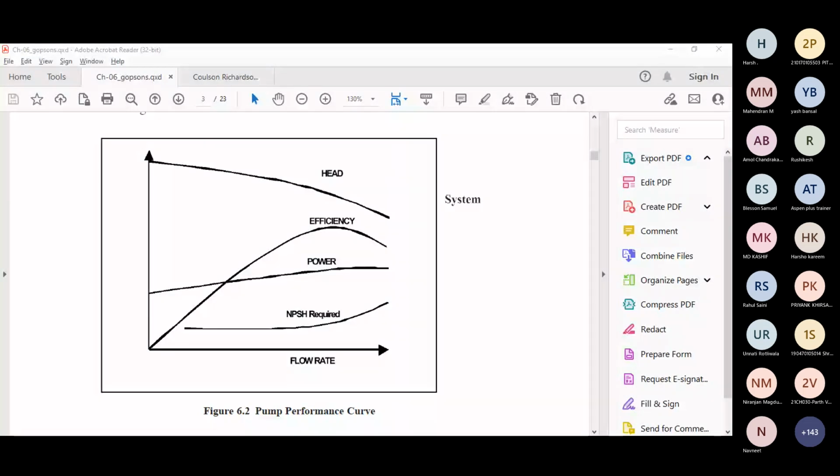Okay. So you mean to say at a particular number of strokes we cannot change the flow rate? It will be the same. Always it will be the same, because at 10 strokes your piston goes up and down 10 times per minute. So what will the flow rate be? The area of the piston and the volume of its casing will pump and displace only that much.